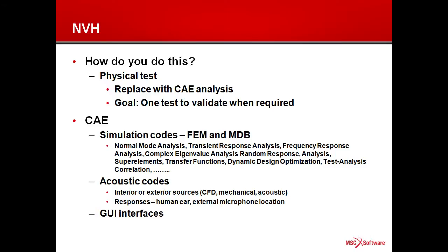Most of it is normal modes and statics. Then it moves up to the dynamics. You're always going to do transient response when you're looking at fatigue. Frequency response, including acoustics, is the noise and vibration part. That's the main piece. There are those who do complex eigenvalue analysis and random responses. Those tend to be a little specialized. Then there are things like super elements, transfer functions, and optimization, which are a little more specialized, but still part of the N&V process.